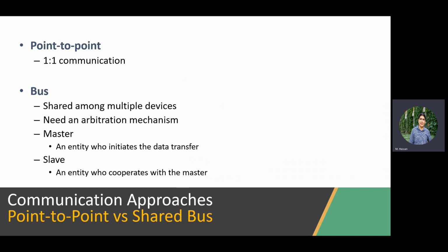So in a point-to-point, this is an interconnect that is very costly, right? And it consumes a lot of power because you have to have wires everywhere. So routing would also be a problem. Think of the highway example I gave. Well, establishing those highways is very costly, right? It's going to eat up a lot of tax money, and they might not be utilized. So underutilization can also be a factor there, right? Is it really true that everyone wants to talk to every other one in the system simultaneously? Well, might not be the case. So why design your system for the worst case?